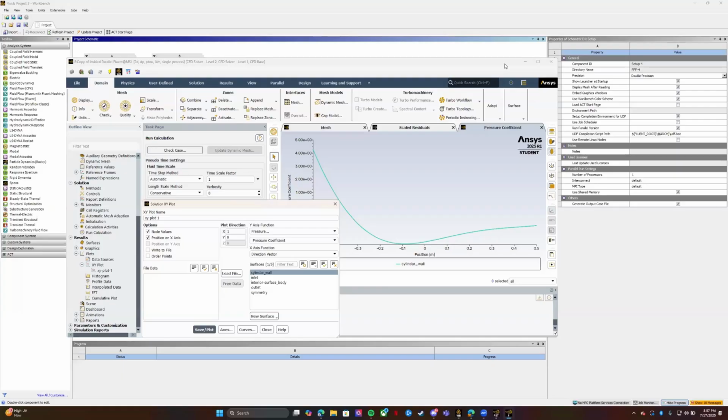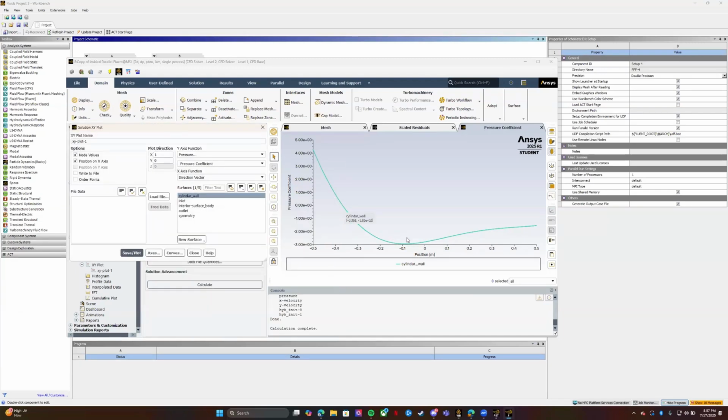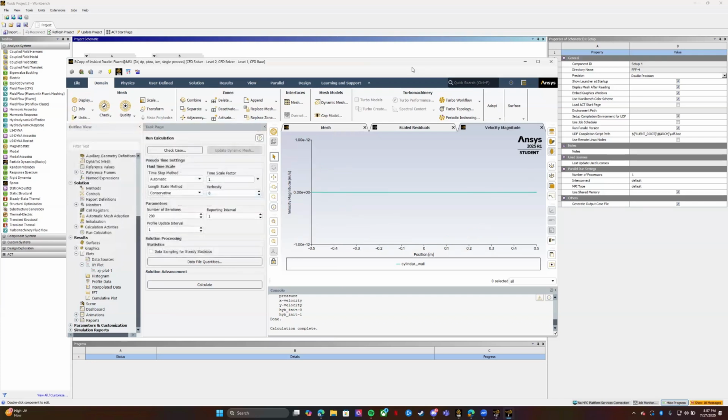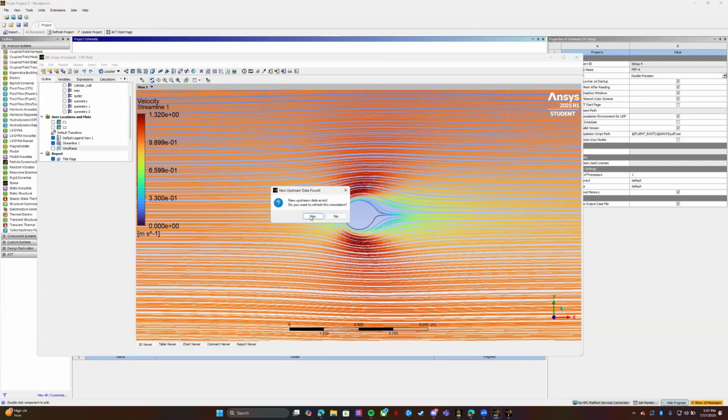Okay, so we just fixed up our number to make our Reynolds number a little bit smaller, and now we're getting the correct shape for that pressure coefficient. Along with that, when we look at the velocity, we should still have that straight line because, like I mentioned, no slip. And then we can go ahead out here and update this system.